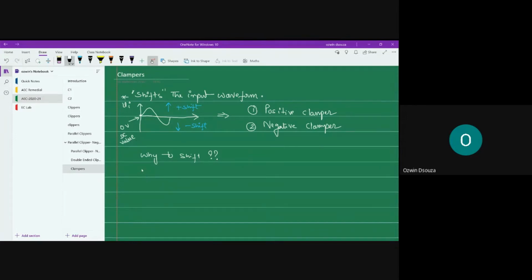So in electric circuits, the widely used waveforms will not have any DC offset value. But on the other hand, in some electronic applications, we go for this shifting of waveform. One such application would be your composite video signal. So what we do is, this video signal